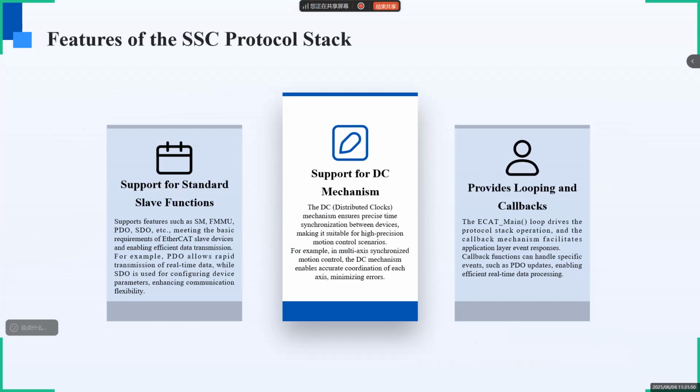The SSC protocol stack meets the basic needs of EtherCAT and can achieve efficient data transmission. For example, PDO can quickly transmit real-time data. SDO is used for configuring device parameters, enhancing communication flexibility.